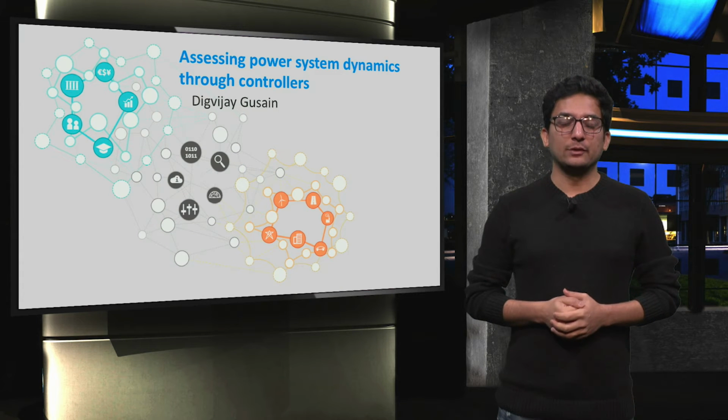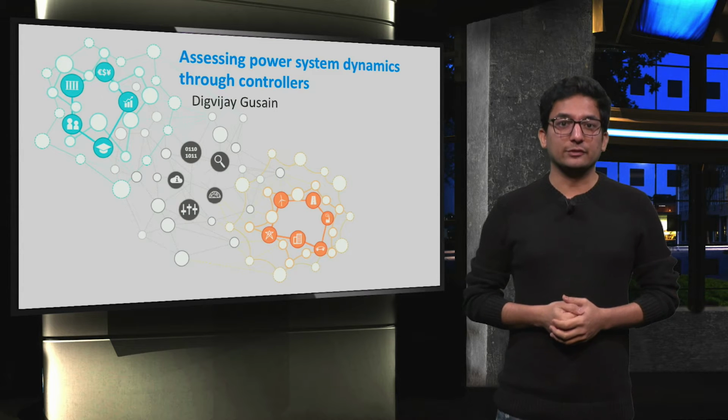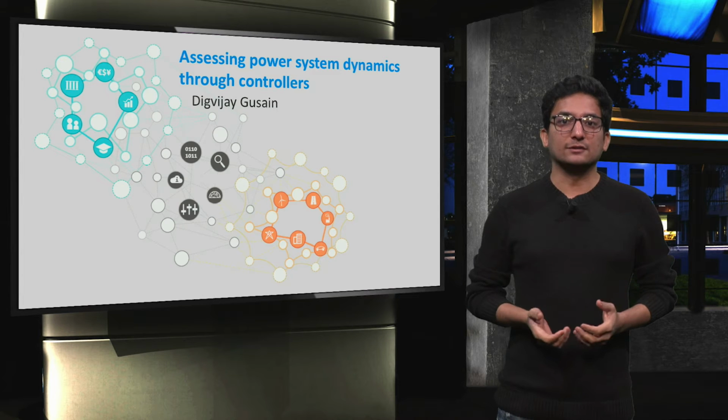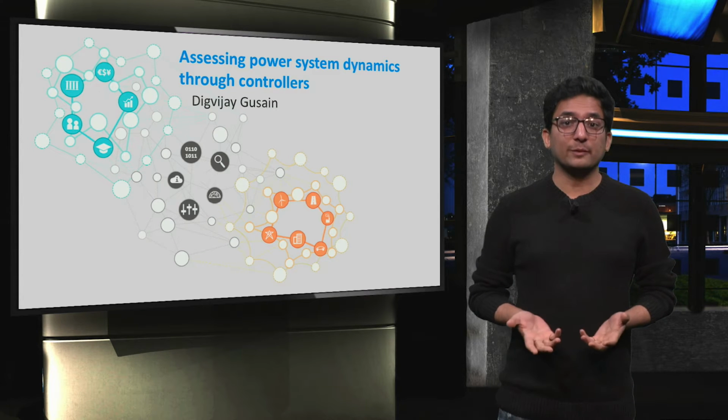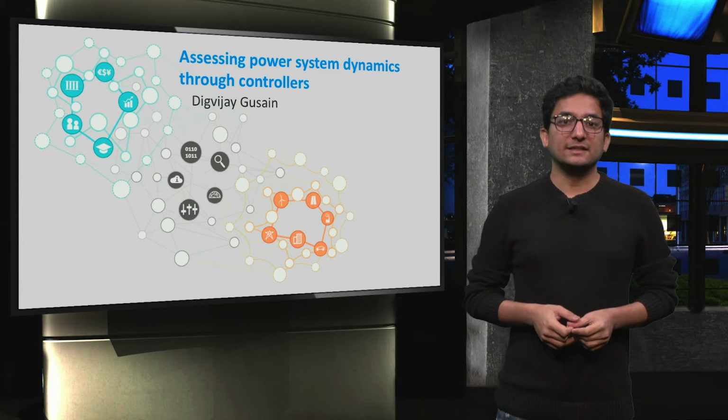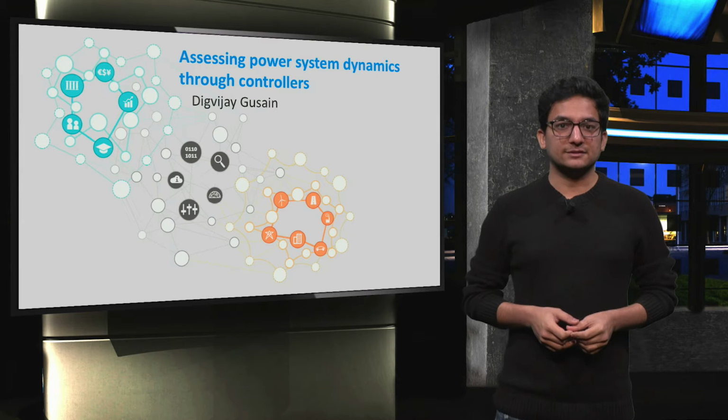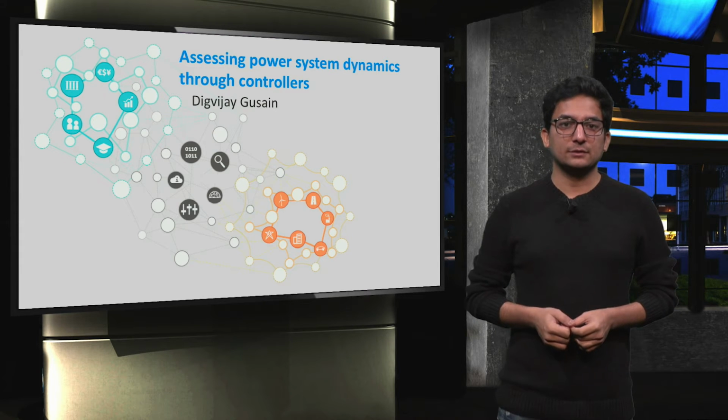In this video, we will build on our model of the IEEE 9-bus system so that we have a look into the control of power systems. We will add dynamic models of the generators with automatic voltage regulators and governor models. This extended model will show how to control the dynamic response of the power system in the event of a disturbance. First, the automatic voltage regulators.